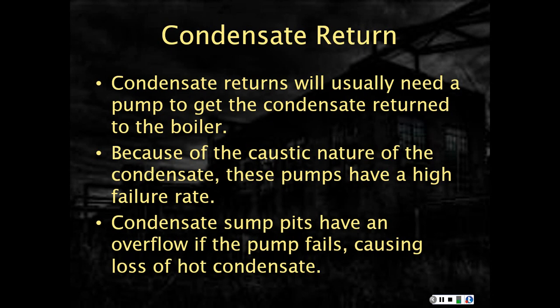Now, condensate returns, if we are returning the condensate back to the boiler, because now we're dealing with a liquid, we don't have that pressure involved anymore, and usually I need some sort of pump to get the condensate back to the boiler. Now, there are some older gravity returns in real small systems, but large systems usually need some sort of pump to get the condensate back to the boiler. Again, because of the caustic nature of condensate, these pumps have a high failure rate.